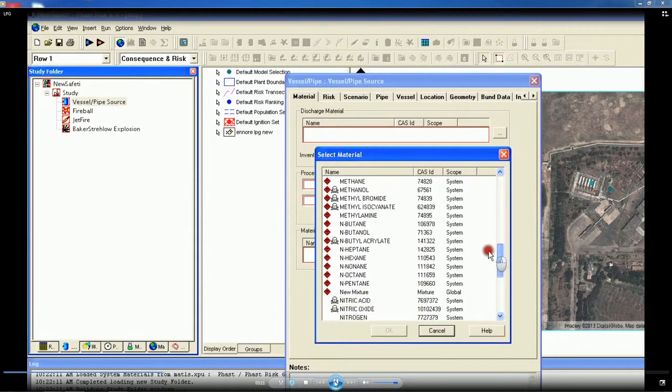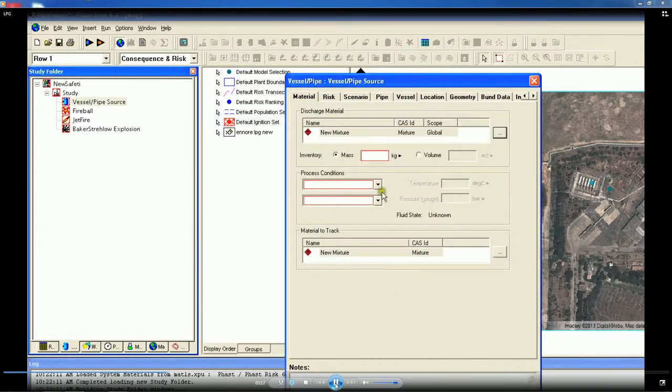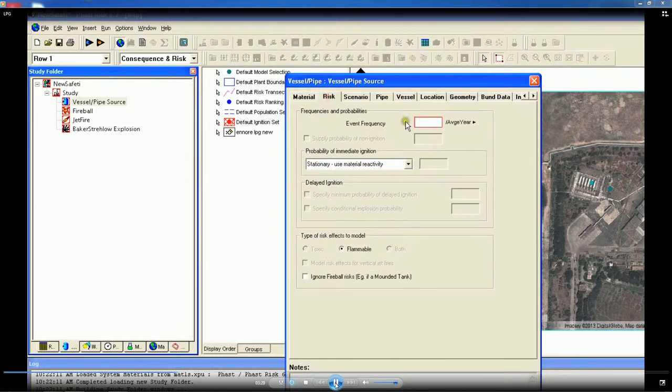We already defined the mixture, therefore the mixture is now available here. As you can see, a new mixture defined by me earlier in the material now has a category of specific composition of butane and propane. So I select that, and inventory mass participating should be given as an input in this case, as I said, is 150 metric ton. The saturated liquid pressure is also given in terms of bar, which is an input for the analysis.